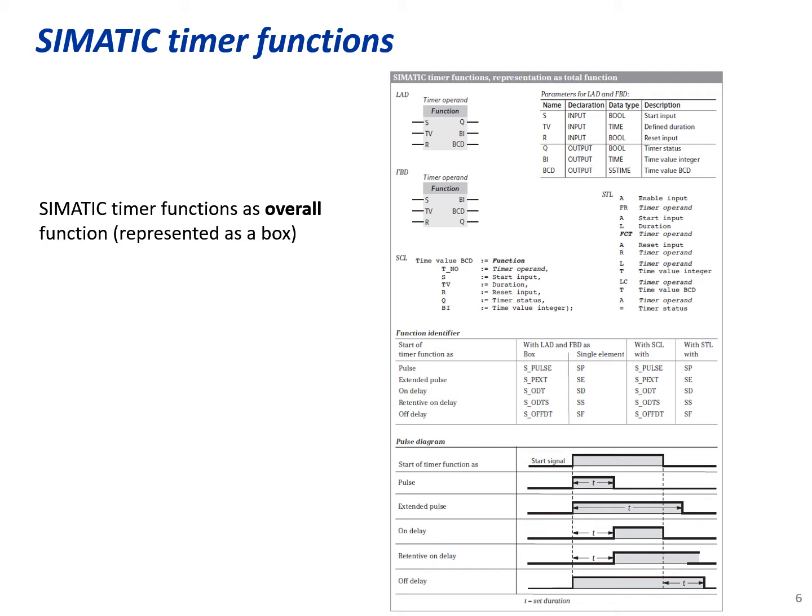Okay, so this is a nice graph that I mentioned in the previous slide that describes different types of timers better than those descriptions. The first signal is the start signal. So in the ladder programming, for example, you see that the first signal is the start signal. This is the signal that triggers the timer.